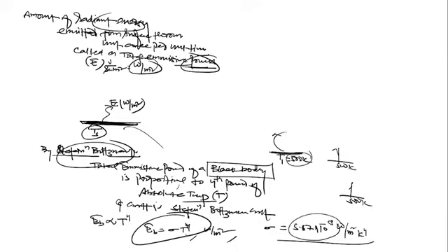This temperature is only absolute temperature. Then that is the upper limit of emissive power. It's not the emissive power of real surfaces, it's the emissive power of black surfaces. All real surfaces emit emissive power less than the upper limit.